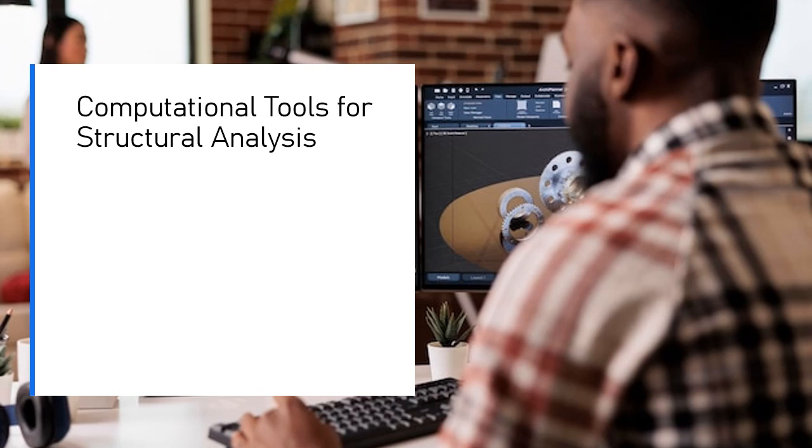3. Structural idealization. In structural analysis, engineers often simplify complex structures by idealizing them as beam column systems, frame structures, or other simpler models. This idealization involves reducing 3D models to 2D or 1D models. In some cases, a 3D structure can be simplified to a 2D plane frame or even a 1D line model, reducing computational complexity.